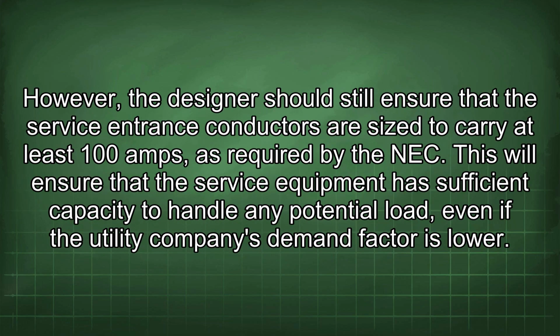However, the designer should still ensure that the service entrance conductors are sized to carry at least 100 amps, as required by the NEC. This will ensure that the service equipment has sufficient capacity to handle any potential load, even if the utility company's demand factor is lower.